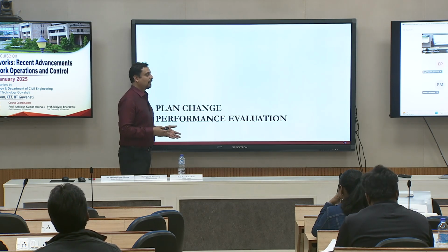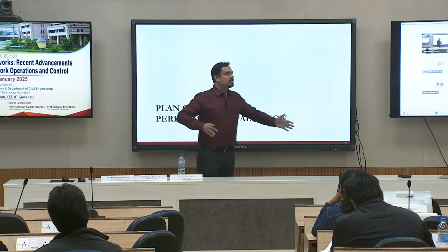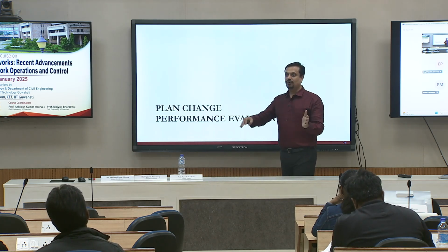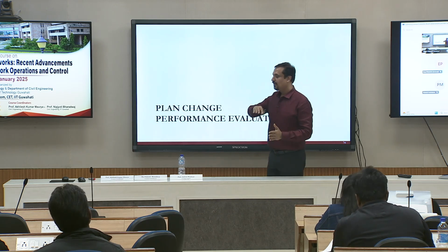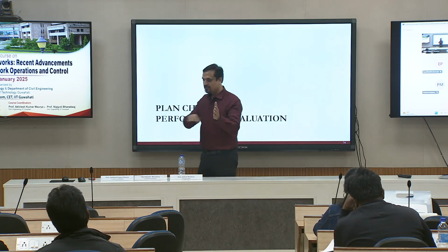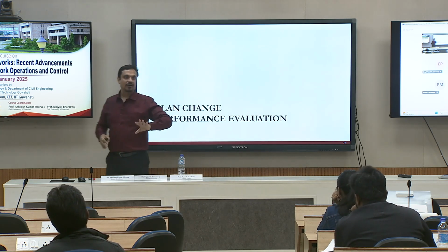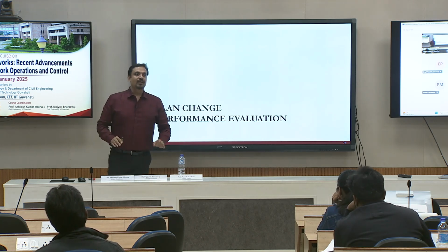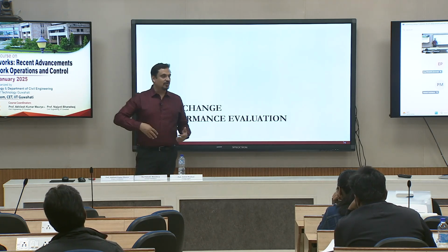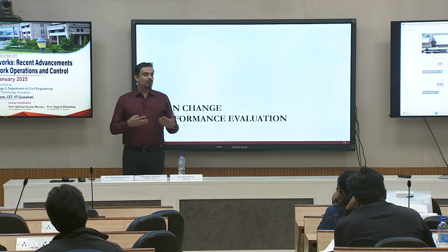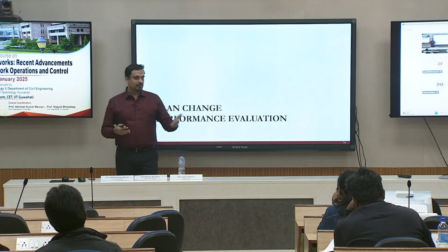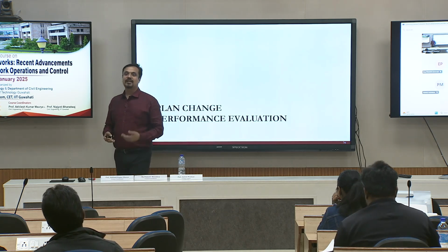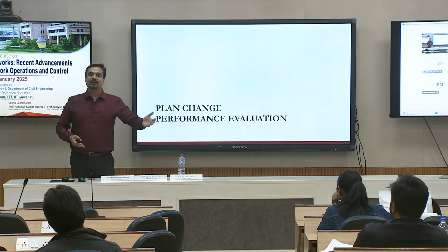Now, on the motorway, as I've shown you, you can draw your space-time plot of speed versus loop detector versus time and get a heat map of the speed plot. You can compare that without ramp metering and with ramp metering, and see how much the improvement was. On the arterials, it's not that easy because you don't trust the loop speed at the intersection. You might have some sources like Bluetooth, or sources like HERE, which give you some travel time or travel speed.